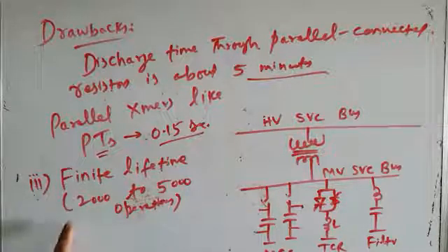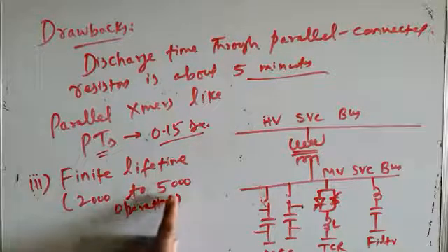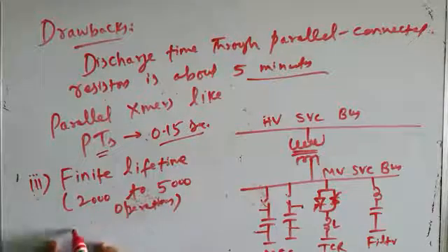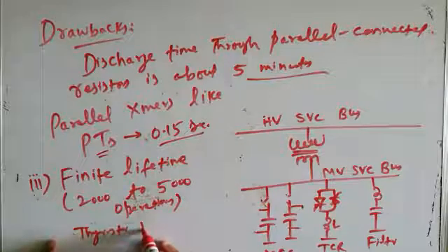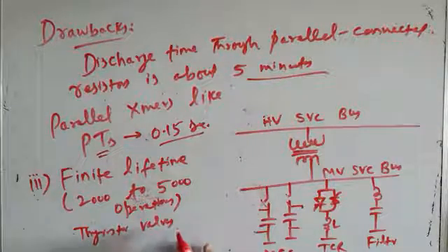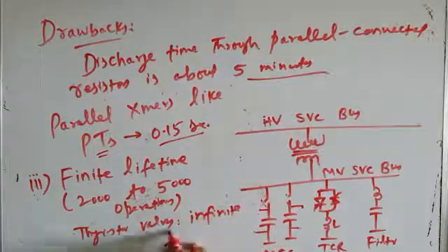And how much lifetime? In terms of switching operations, about 2000 to 5000 switching operations only. On the other hand, the thyristor valves used as switches in thyristor switched capacitors ideally have infinite lifetime.